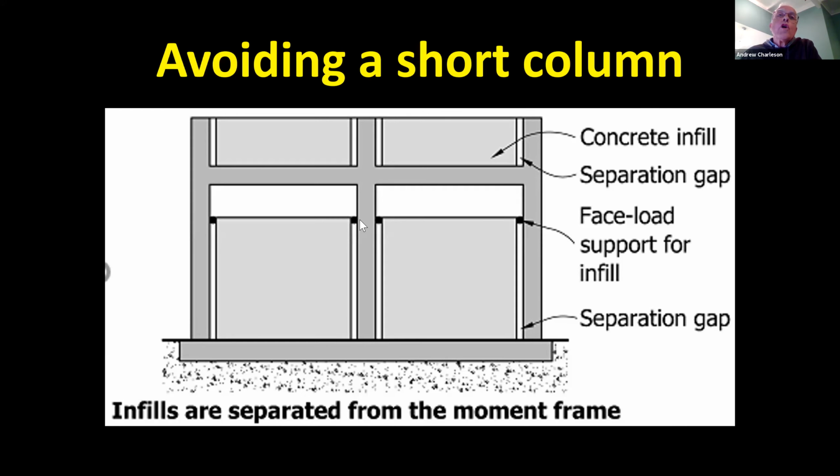And so you create the gap and then you would fill it with polystyrene, or maybe you would fill it with a fire-resistant fibrous material. And then you could apply sealant